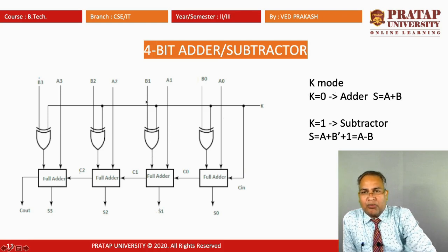So, the output of this XOR gate will be B, and this output goes to the full adder, and the next input is given by register A. So, there are two inputs: first the output of this XOR gate, next the input from this register, and the third input is the carry in, which in the beginning we take as 0 for the adder. Because this is the diagram of the full adder, it needs 3 inputs.